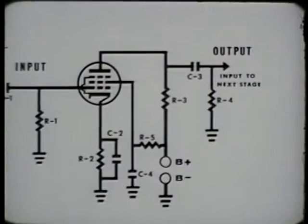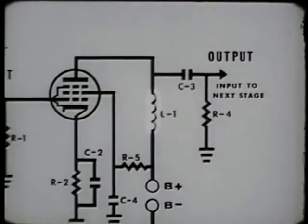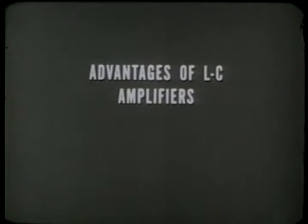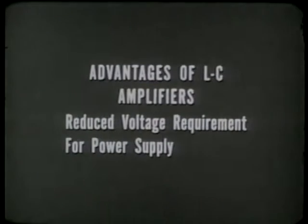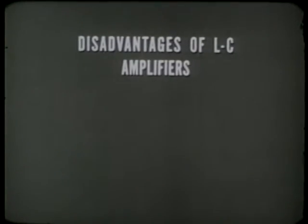Now let's change the plate load resistor to an inductor, and we have an impedance coupled, or LC, amplifier. LC amplifiers have one particular advantage. Removal of the plate load resistor reduces the voltage required from the power supply. However, LC amplifiers have a disadvantage.